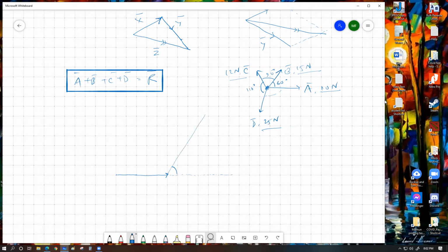And then along this line, we should draw a 50 Newton force, which should be, in this case, I took 1 division for 2. So this should be 7.5 divisions long. So 2, 4, 6, 7.5. If I take about an arc of this much length, about this much. About. So let's say this is our vector B. Then from this point, this would be the direction for vector B.